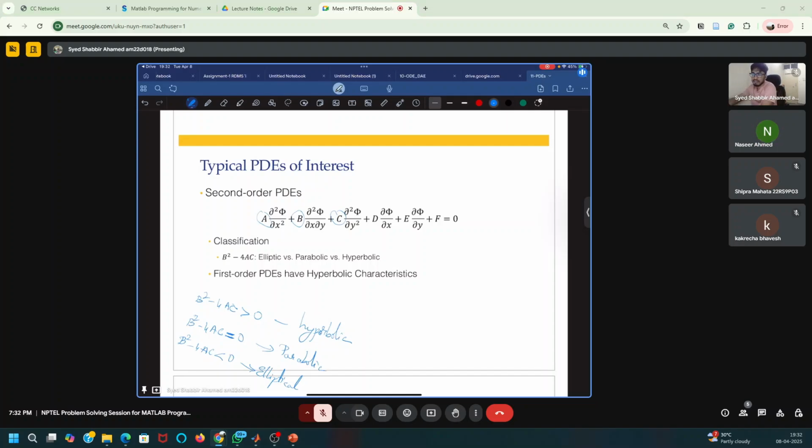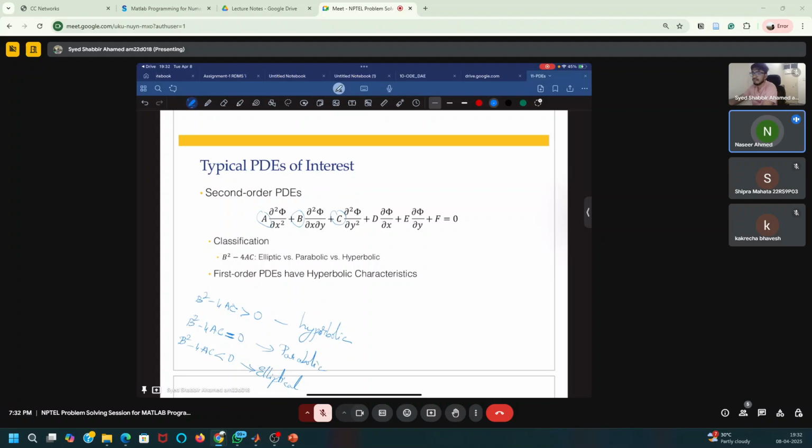Three-dimensional with time is unsteady flow, because as soon as we say time is there, it is unsteady. Actually, I worked on viscoelastic fluid, and viscoelastic effects come into the picture only in unsteady flow. As soon as it is steady flow, the viscoelastic effect vanishes and it becomes a Newtonian fluid.